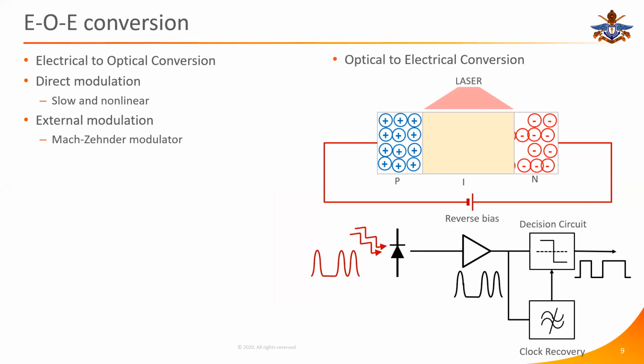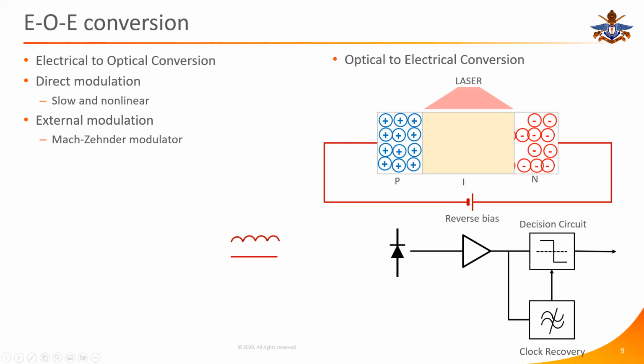In modern telecommunications, and I will get to this again in another two weeks' time, we no longer use amplitude shifting. Amplitude shifting means if you have a series of ones and zeros of electrical data, we create similar optical pulses and no pulses in the optical data. Instead of doing that, we can create phase changes, and we can recover that. This is the technique used in modern communication systems. I will get to that later on next week.